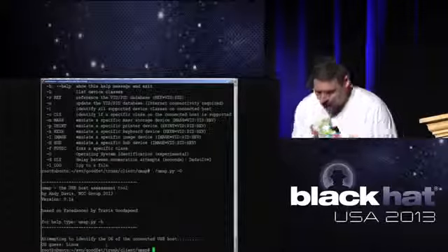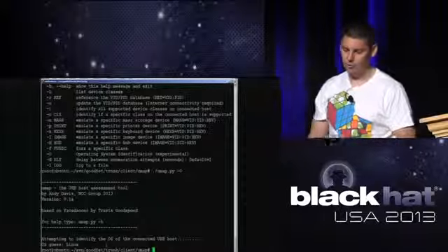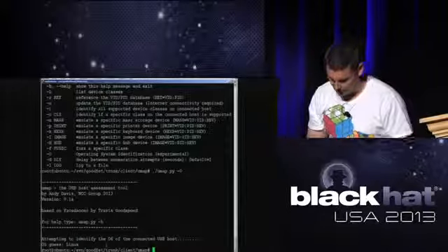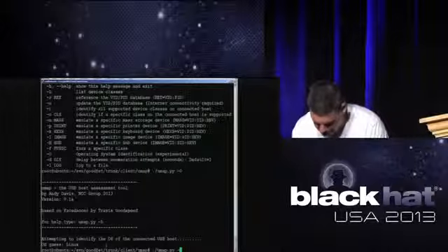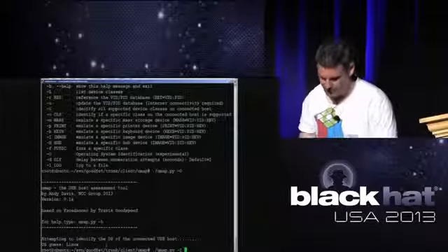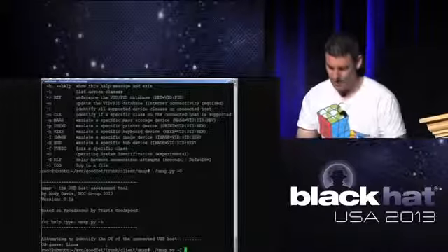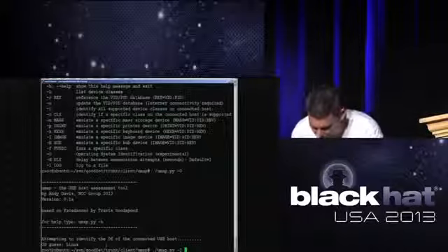If you want to specifically emulate a device, let's say I want to just pretend to be an image class device, I can say just be an image class. I need to provide the VID, the PID, and another element called revision, which isn't particularly important.